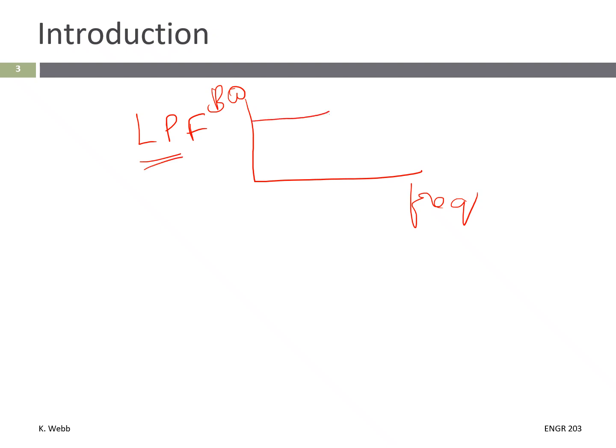So these types are classified based on the output that is achieved from the filter. Low pass filter: when a signal of any range of frequency is passed into an operational amplifier coupled with resistors and capacitors, the frequency response obtained in this kind of low pass filter is that only the lower frequency signals are allowed and the higher frequency signals are blocked.